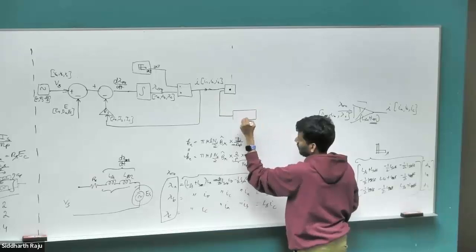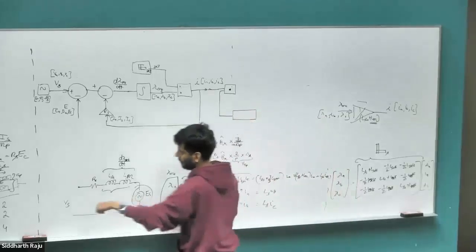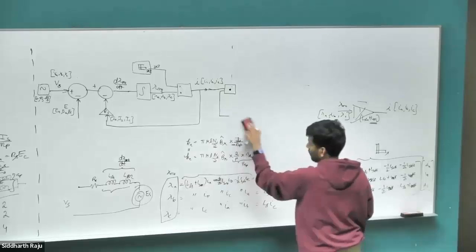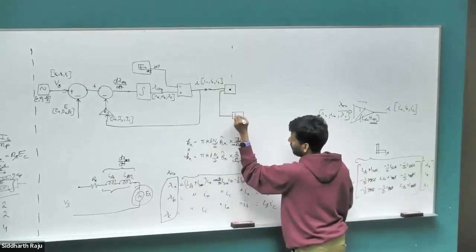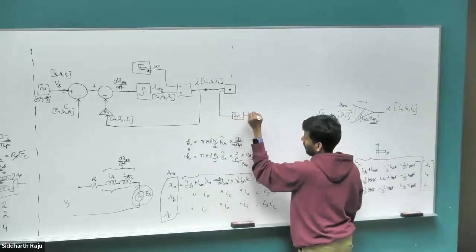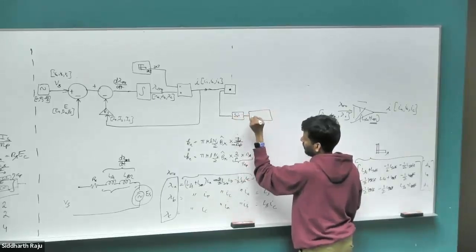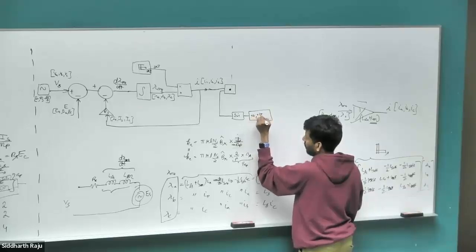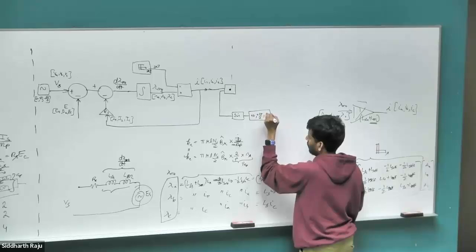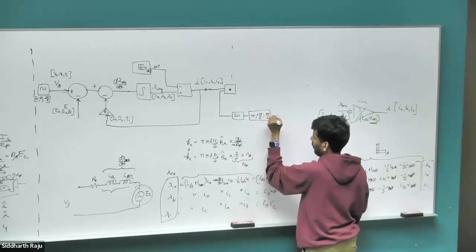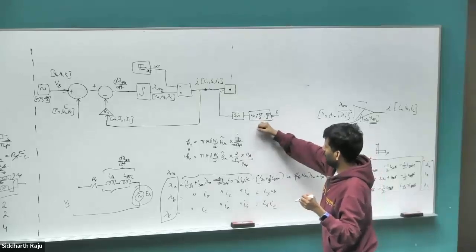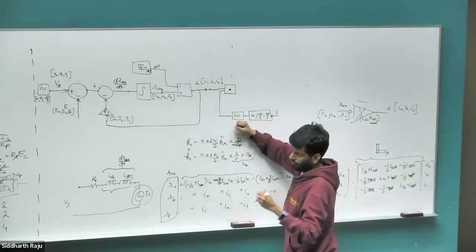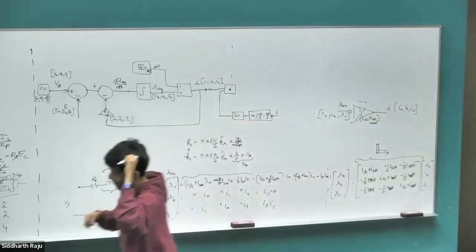So you can have a sine block, and you can offset the values by 0, by 2 pi by 3, and by 4 pi by 3 using an offset block, and the input of this would be delta. So you take delta plus 0, delta plus 2 pi by 3, delta plus 4 pi by 3, take the sine of it, so you end up with sine of delta, this is the equation that we have right here.